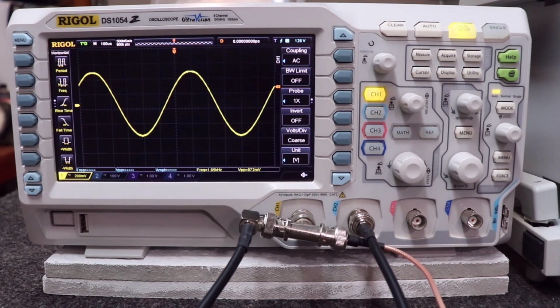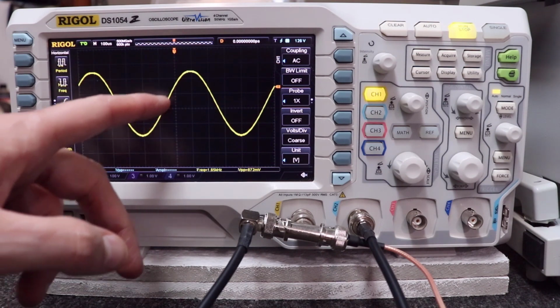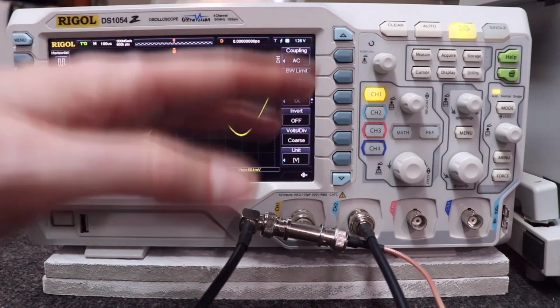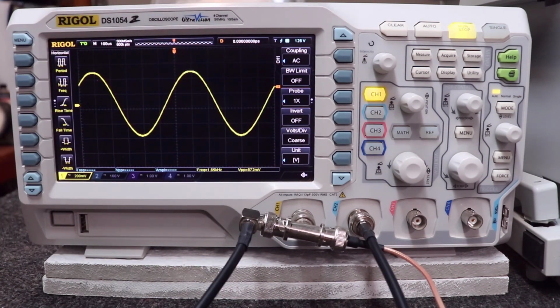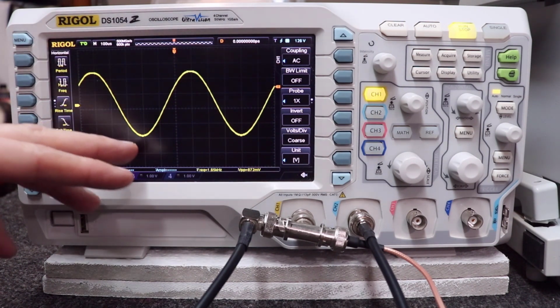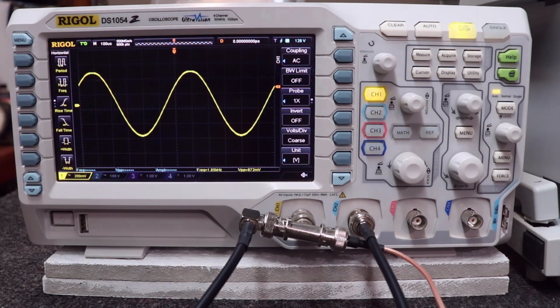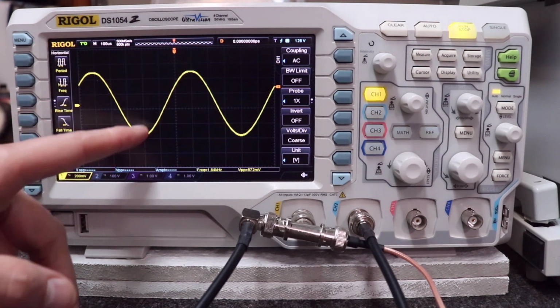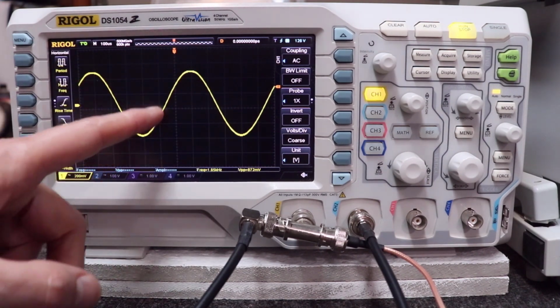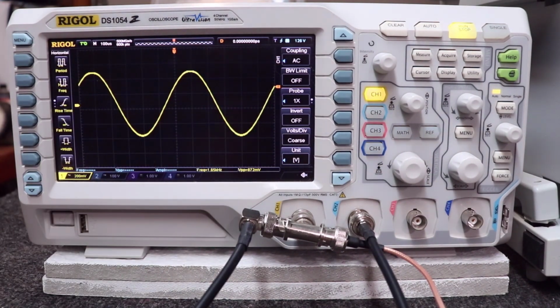Well, the reality is the cathode ray tube just takes longer for the fluorescence to fade out, so it always looks nice and smooth. So there's a smoothing factor that happens on a CRT based oscilloscope just from the fluorescence and how long it takes to go away. And this may be actually a little more accurate. However, there is the resolution of the LCD here that you actually have to deal with.